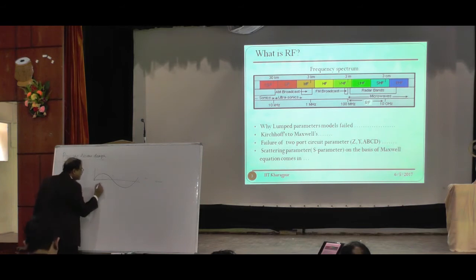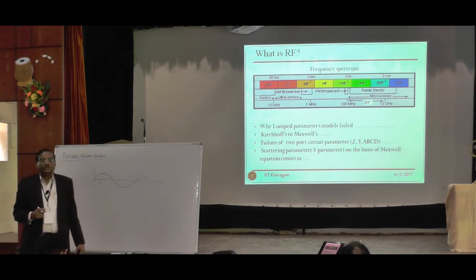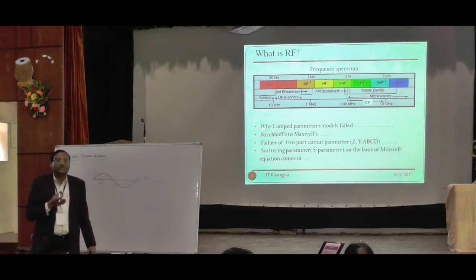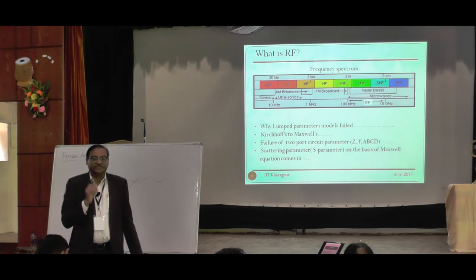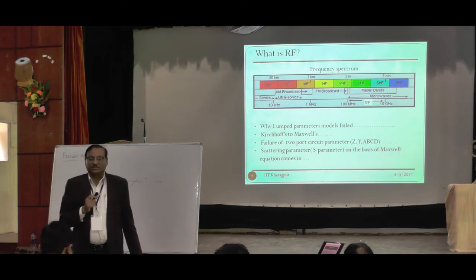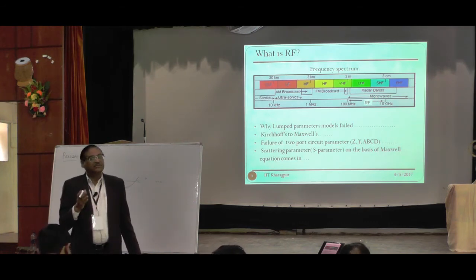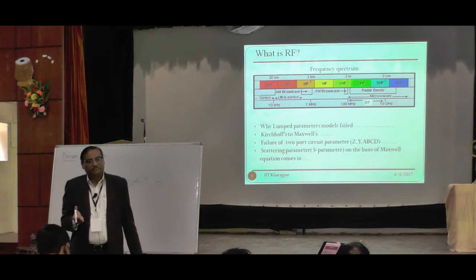Look at this, if the component size is here, and if you look at the change of the phase, it is almost negligible. Yes or no? The change of phase along the length of the component is almost negligible. When a voltage is applied across a resistance, is there any change in phase? The current and the voltage are in the same phase. But whenever an AC voltage is fed to a capacitance or an inductor, what will happen? You will see that your voltage and current, in one case it is phase lag, in the other case it is leading.